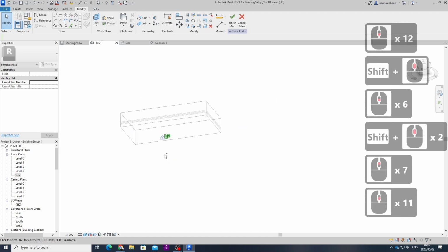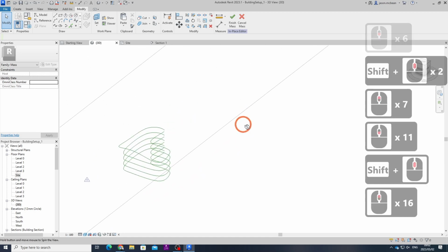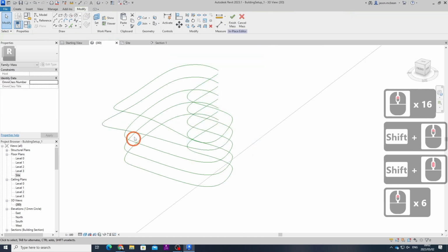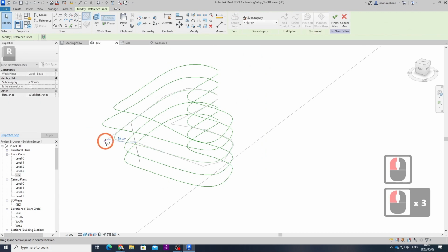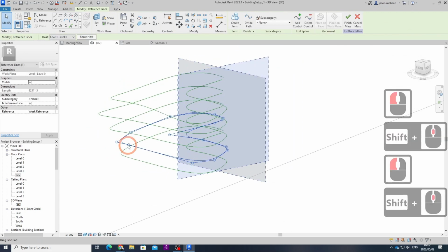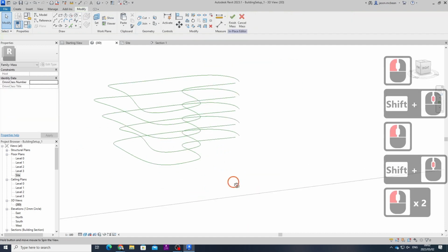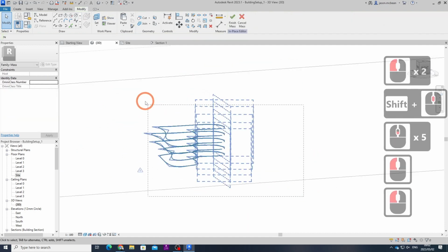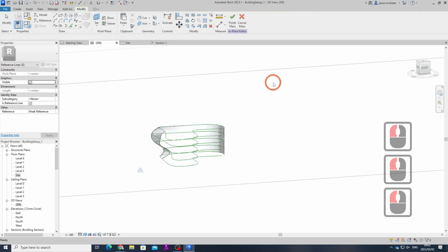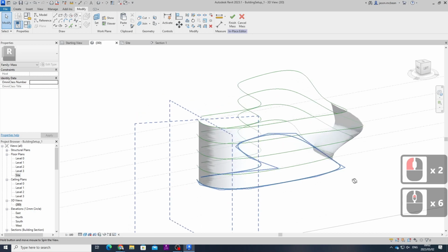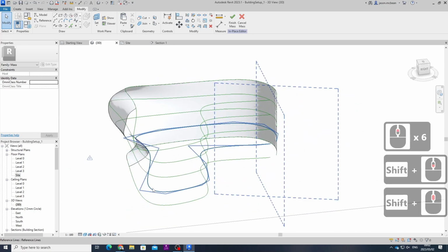Okay, I'm cutting through this as a section at the moment, so that's probably why we can't see it. That explains a lot. Good. Now, I can grab this one. I can make some slight adjustments to this one. I know I'm cutting into the neighboring building, but I'm just trying to demonstrate the power of using these types of forms. When I select all of these forms, and I use this command over here, you would have noticed it created a very organic type form following that shape.